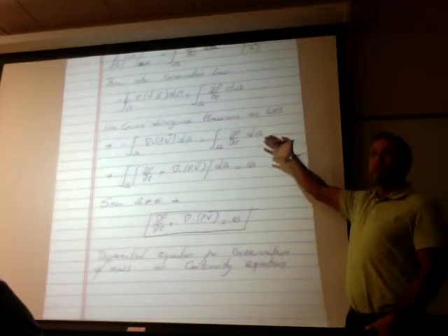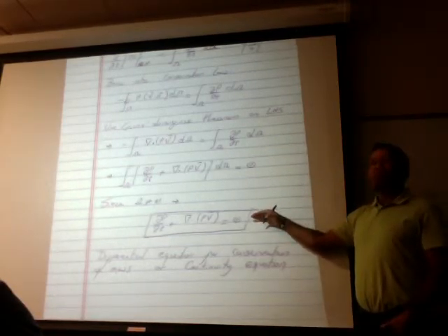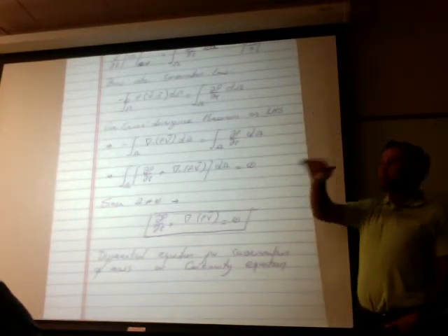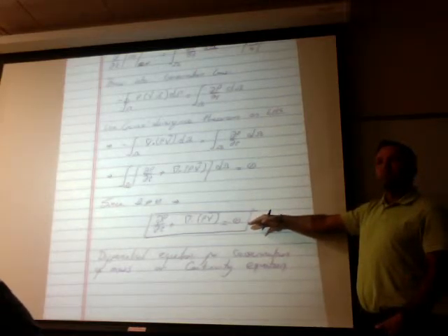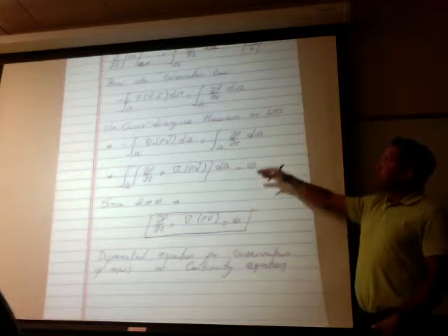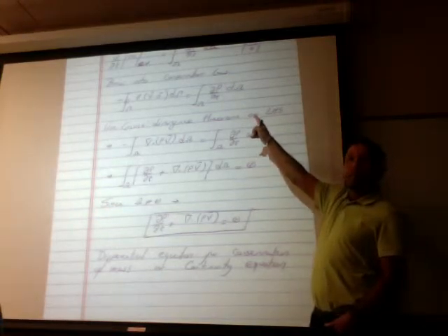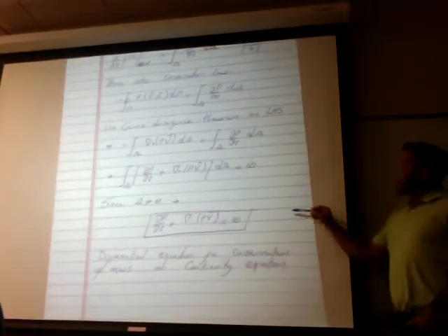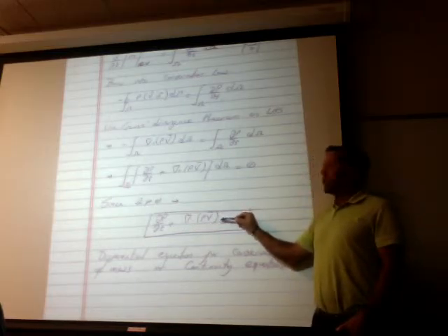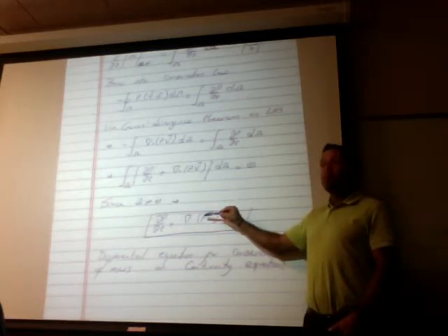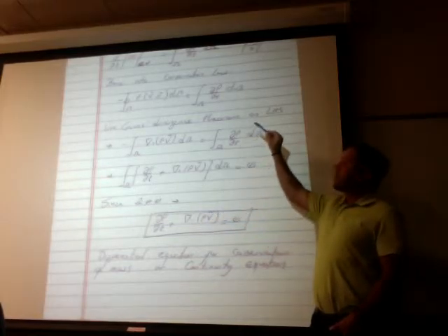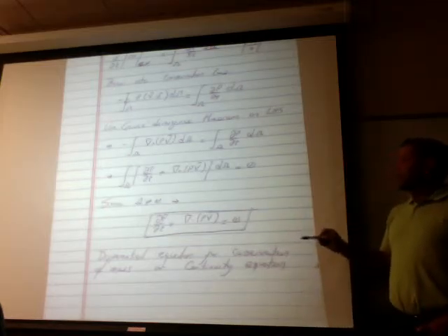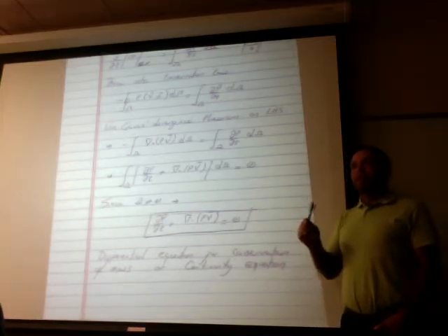And there are some other methods, like the finite differencing method, that use the strong form as a point of departure. Okay? So finite differencing techniques, which are the oldest numerical techniques, use this as a point of departure for the formulation of the method. And finite elements and finite volumes use the weak form of the equation to get to the answer. Finite differencing uses the strong form, and therefore gives you a solution that is constrained and is accurate at every point. However, they actually lack global conservation. Therefore, you might solve a problem of fluid mechanics using finite differencing, get right solutions at every point, and find out that you're losing mass.